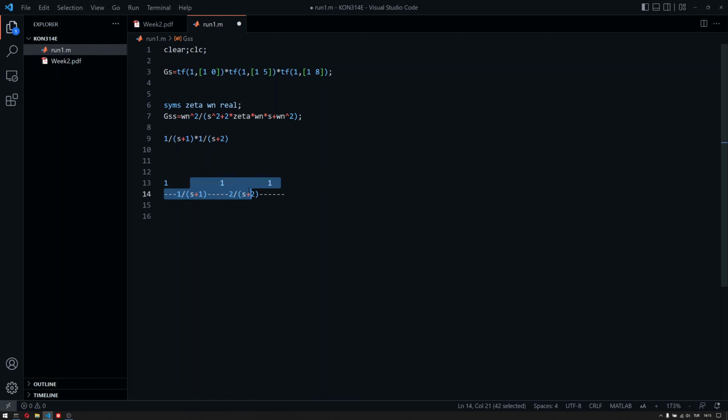So if we have real roots, what really happens is that we will have just connected first order transfer functions to each other in series. So therefore we would just conclude that, of course, this will not overshoot, and we can see that. But in the case of complex conjugate pairs, this is not really the outcome. We will have oscillations and overshoot.